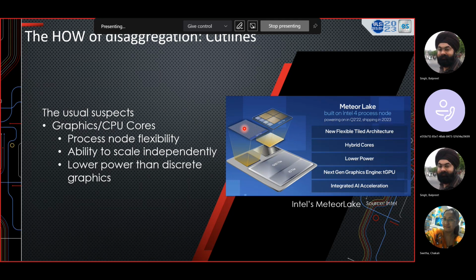At least, I mean, for very high frequency TSVs, I don't know, maybe Biswajit can talk about that. TSVs will probably not meet it. Again, case by case, we can discuss offline. But if you think about it, a TSV is nothing but around 20 milliohm to 40 milliohm resistance, about 20 to 30 picohenry of inductance, and the coupling is almost negligible. With that kind of R and L, it is going to impact your performance.